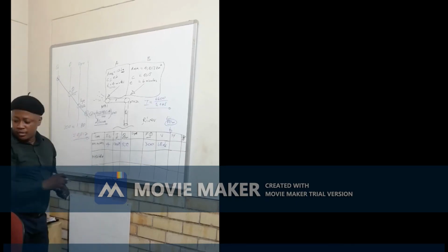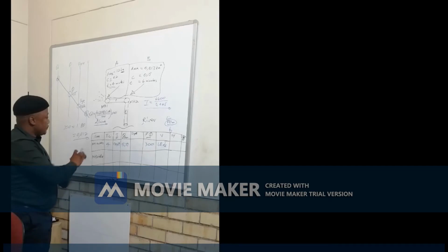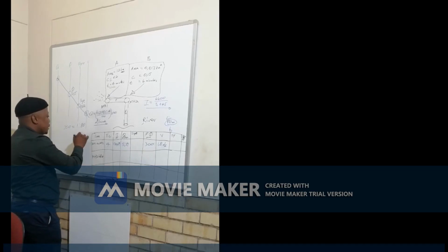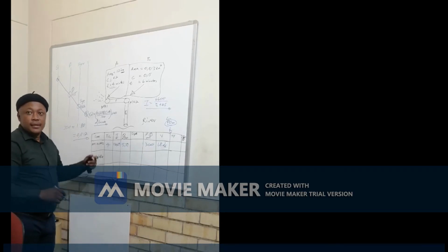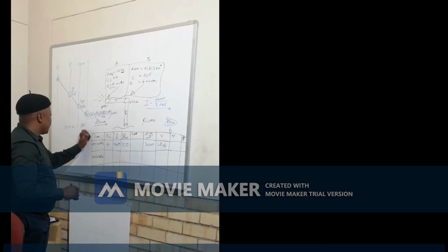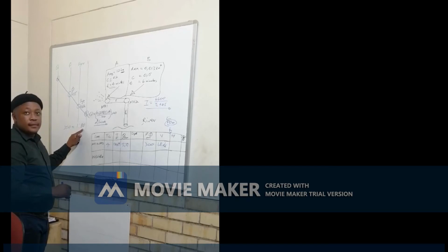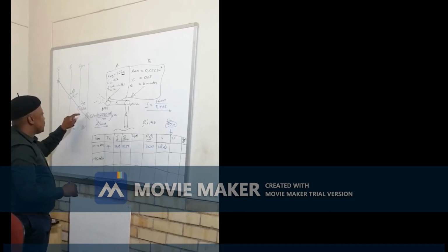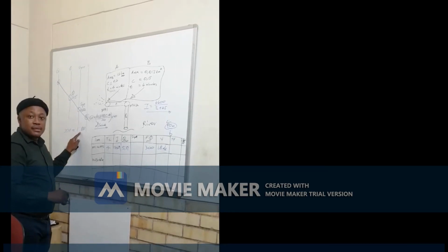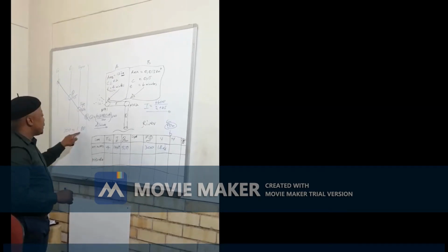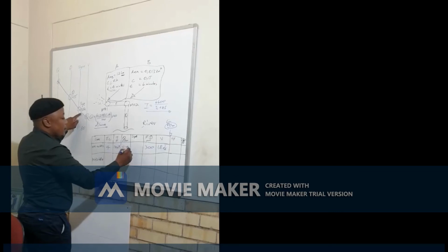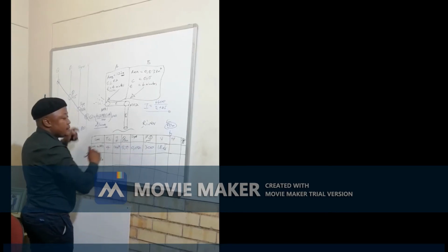Probably 1.2, I'm not too sure. Let me check quickly. Yeah, looks like 0.012. But now, the same calculation that you might be having, if you look in terms of the slope there, that one becomes our minimum acceptable slope in terms of that diameter, and our design slope is bigger than the minimum. Hence, we adopt our design slope and keep it as it is.